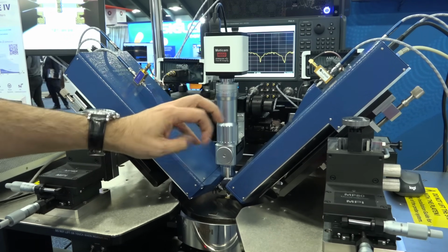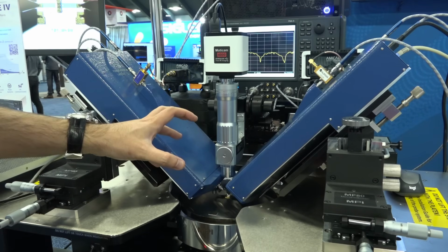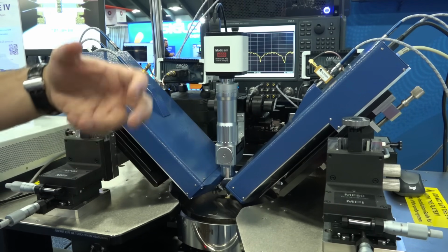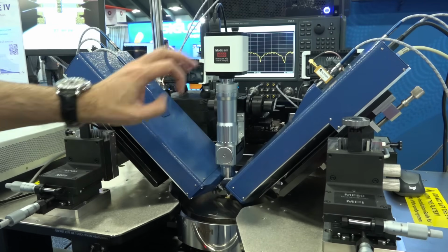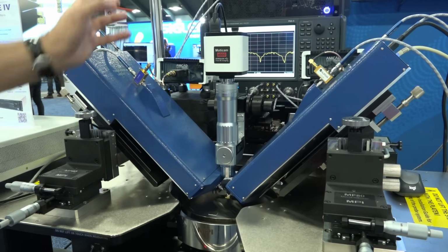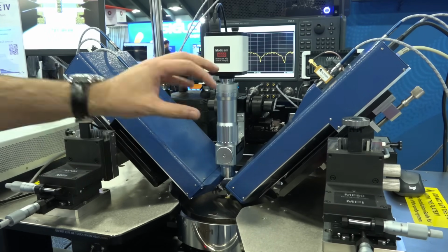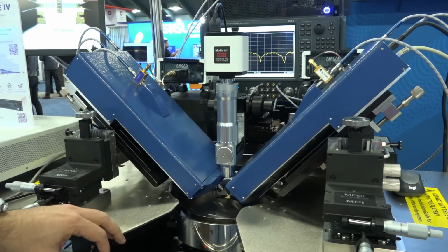So any unusual things that happen in the device due to trap effects will actually be captured because of that RF pulse now being applied. So you have a two-step measurement where you've done a complete load pull, you save that, then you do your RF pulse measurement, you combine that, and then from that you can do your validation, you can do your parameter extraction, but then you will see the exact dynamic behavior of a system.